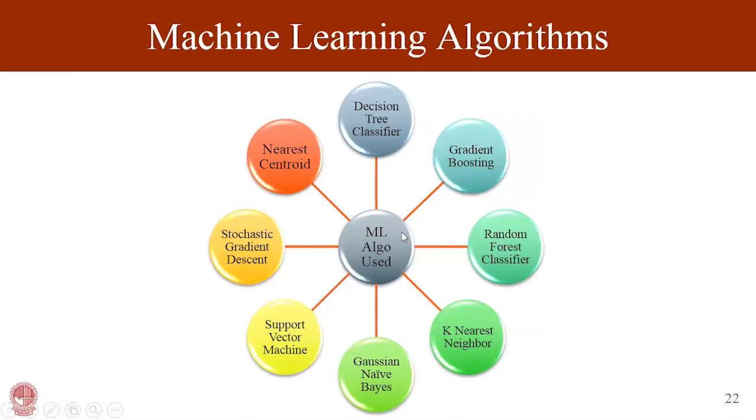So from those two analyses, the first analysis and the statistical analysis, we can be sure that there may be a completely different vibration pattern during different machine faults. So we thought, why don't we apply this data set to machine learning algorithms, since machine learning algorithms can learn the vibration pattern during different faults. And using that, it can detect the type of fault occurring in the machine, so that we can detect the fault in the machine's working.